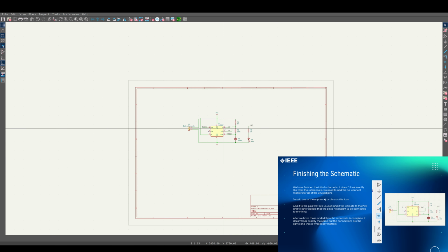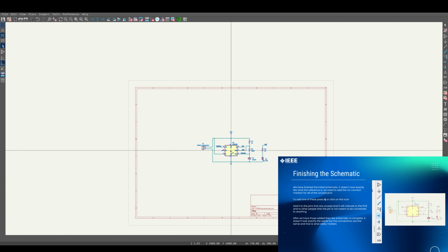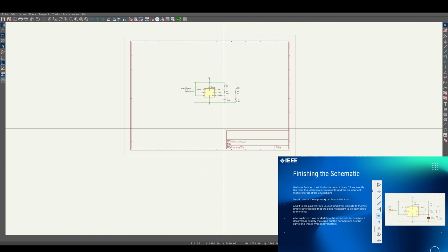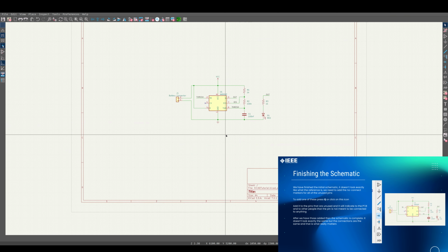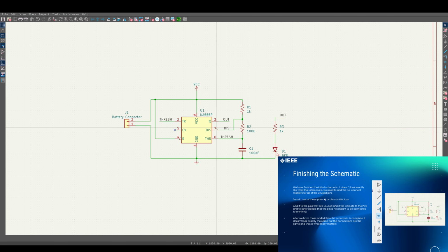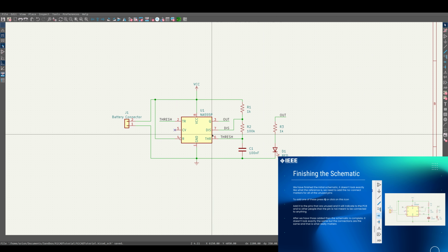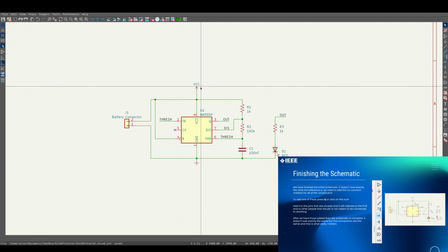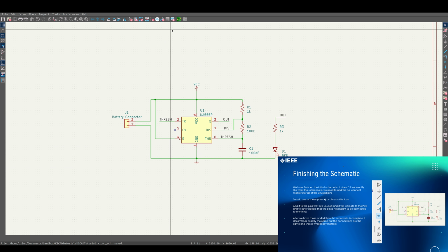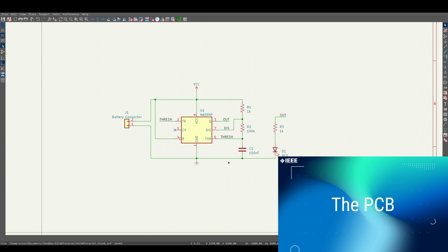After that, that's basically it. Maybe move it over, move it down or something to middle or something. It doesn't really matter. Oh yeah, here, make sure to press Control S, Command S to save, and then make sure to double check it against the schematic, and I say, oh, it looks pretty good. This looks almost exactly the same as the example provided, but that's part of the idea, right? So next step, I believe, is to start actually talking about PCB. Now we're going to go over to the PCB editor.